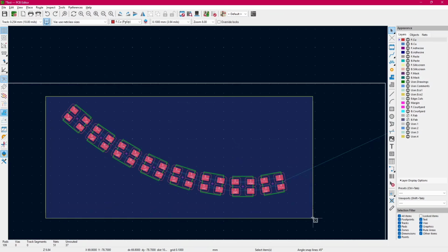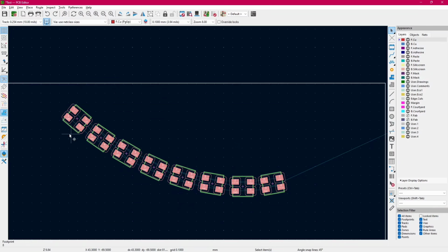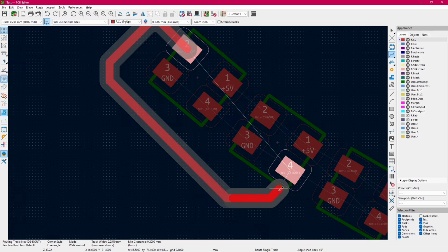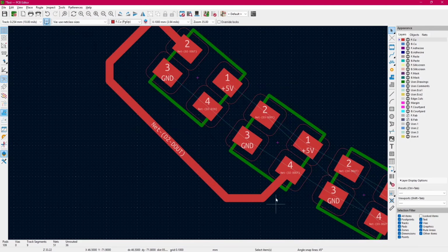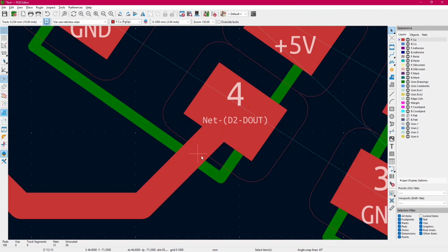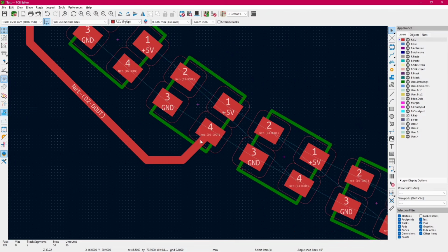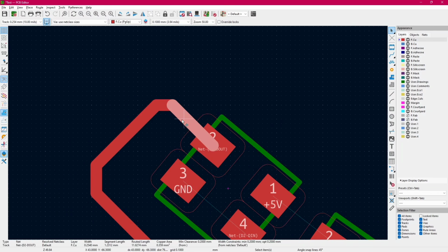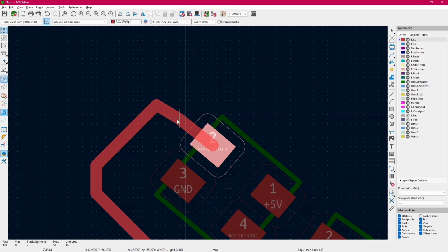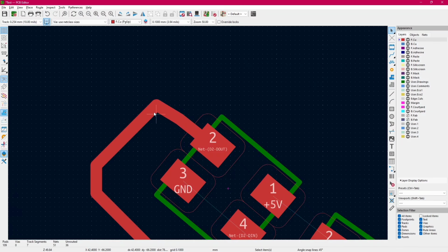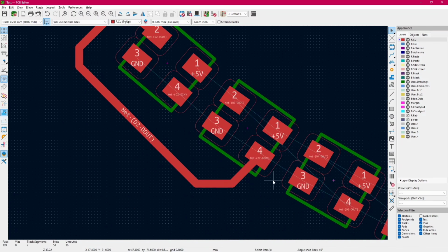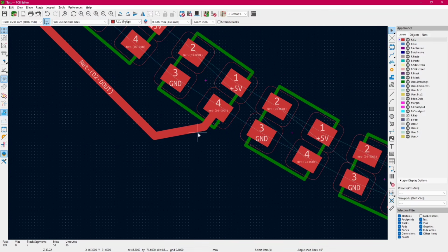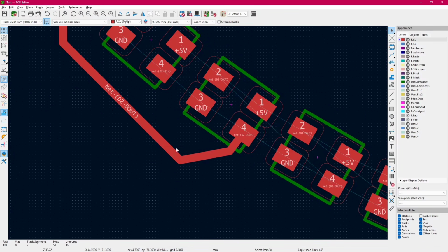It can sometimes happen to have a layout of components like this one, so if we try to connect those LEDs, you can see that it doesn't really connect well. You can see here the angle is not really good. So one way to fix this is to use the G key to enter the free angle mode, and you can see now it connects really well. We can do the same to the other end. We can press G and there we go. Now it connects really well.